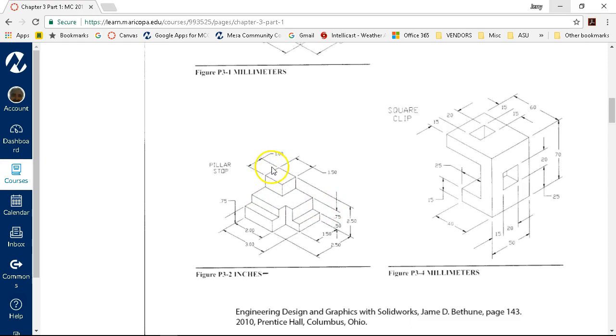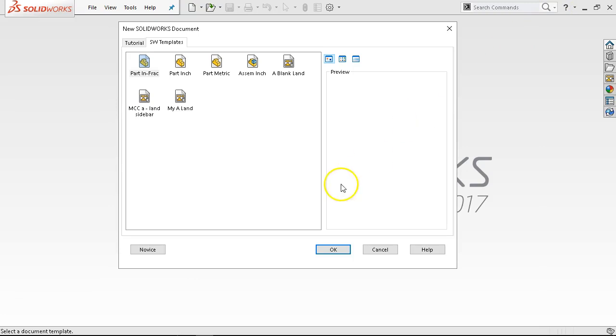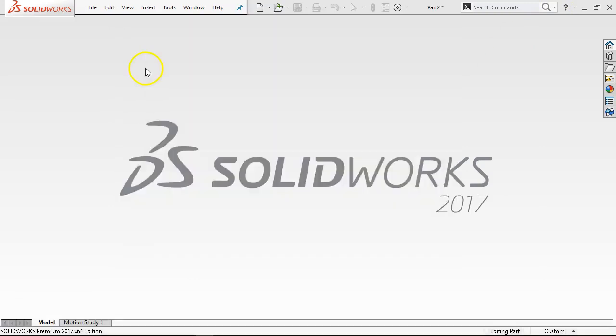If we wanted to, we could start off with a cube that was 3 by 2.5 by 2.5 and whittle away the material. That is a good strategy if you're going to illustrate machining processes. I want you to set it up this way first, and depending on the complexity of the part, go through the process of remove this material, second step, remove this material, third step, remove this material. So we're cutting and whittling away at the part. But for the most part, we're going to keep adding geometry, and this was 1 inch.